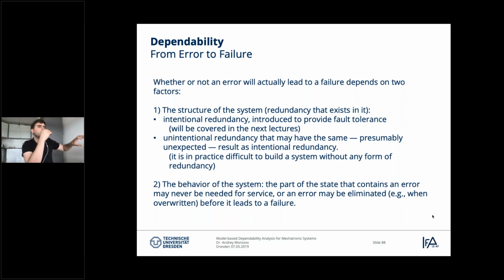So we add additional redundant sensors, or in the same way we can add a redundant controller or redundant actuator. We could even have redundant motors in planes. For example, planes with propellers can usually still fly with one propeller, and this is redundancy. This is how errors are masked because of the redundant structures.